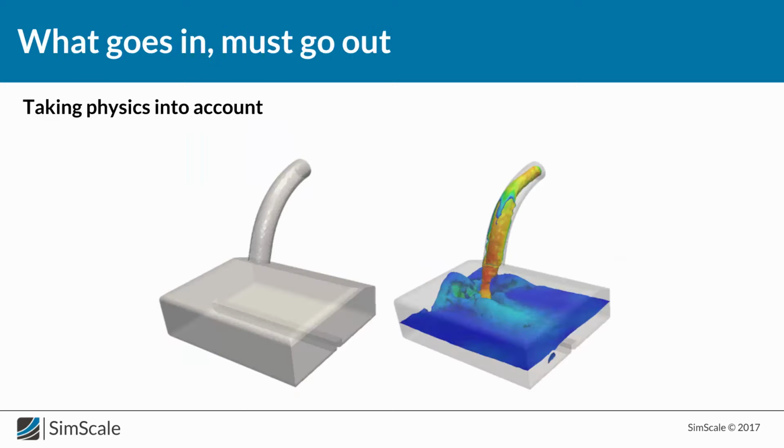Finally, we need to consider what's going on within the domain and the physics that is going on. Let's say that we would like to model a filling of a tank, or in some cases, let's say we are putting a cleaning gas into a clean room. At the very beginning, there is nothing in the tank. Is it? In fact, we are having air inside, and when we start pushing anything into the domain, we will need to remove the remaining air from it. That's why we should consider always putting an outlet that will allow the residual part to move away.